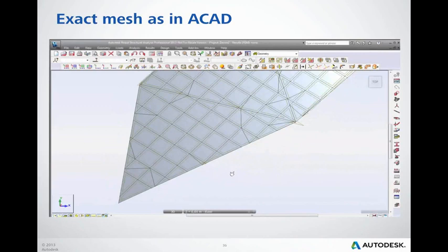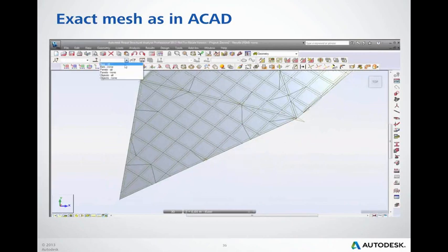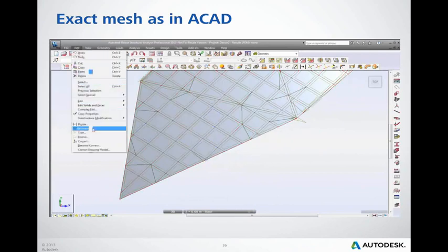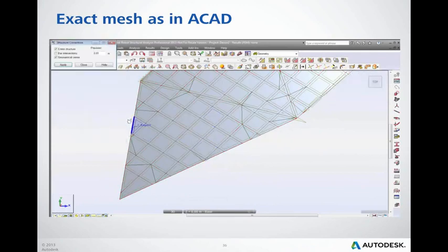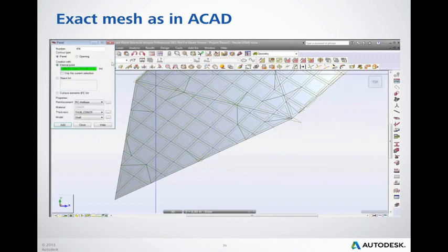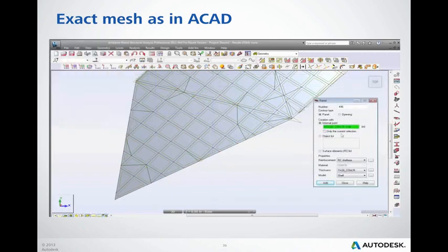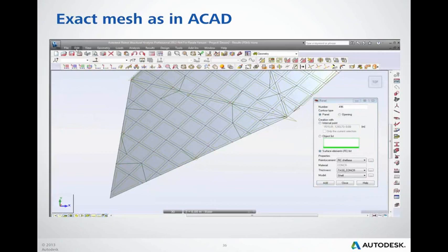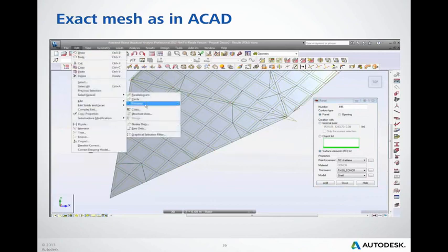Now we can easily delete all remaining bars which were important as temporary bars. And now, to avoid a high number of panels inside the model, we can reduce them by creating one outer panel from the selection. So we need to create the new panel from the selection of finite elements.